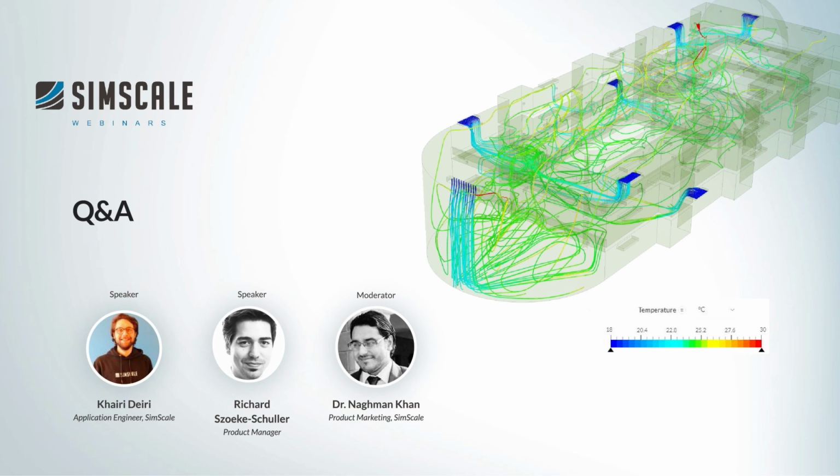Yeah, I think energy modeling tools are great for assessing long periods, right? To assess what is the overall energy use of a building over the full year, right? That's not something you can do with CFD. CFD is good if you want to have a look at one specific point in time of one scenario and see what is the detailed behavior within the space, right? How do people feel when they sit next to the window versus a bit lower to the left, where there might be some downdraft from some inlet from the HVAC system and so on, or outlet.